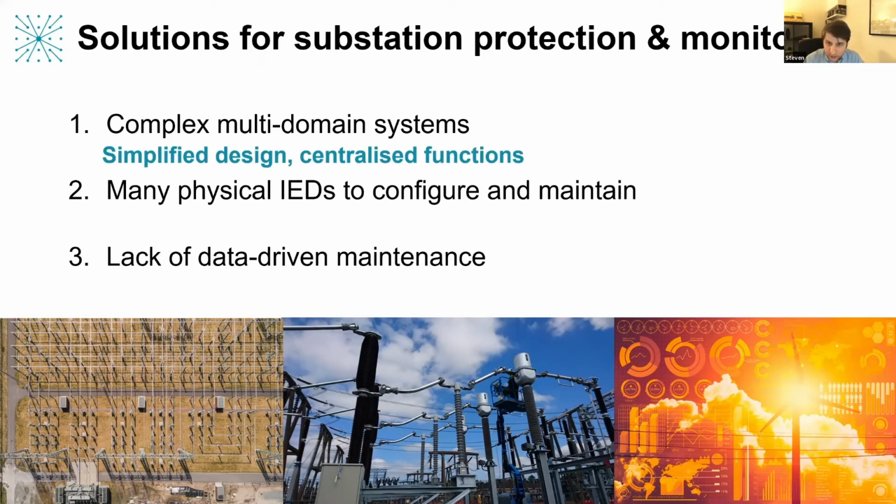So first of all, with that complex multi-domain knowledge that's required to make this happen, what we're offering is a greatly simplified design through passive sensing, and something that's a natural fit for centralized substations, and will really deliver efficiency gains in the long term. And similar to that, we're consolidating multiple physical IEDs, in particular the merging units, which are normally needed, into a much smaller number of devices. So that means it's easier to maintain over time and to configure in the first place.